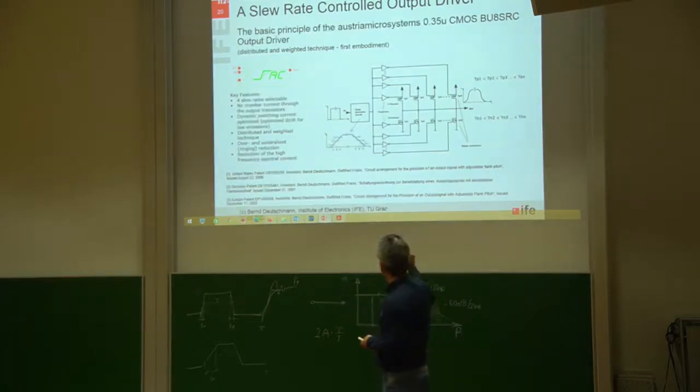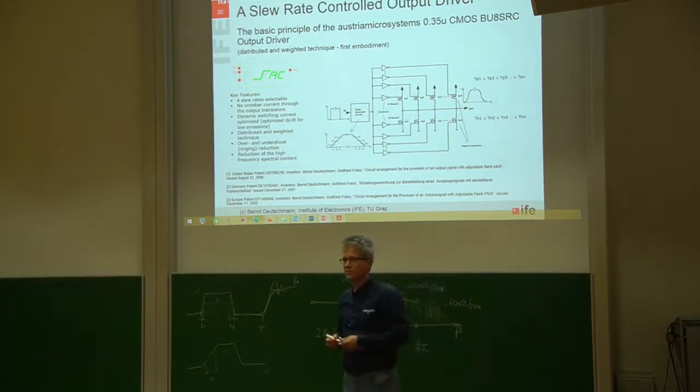Then a little bit later, in parallel, I'm turning on this next P-channel transistor, so the little bit bigger one. Then this P-channel transistor is turned on, and then in the final stage, the last P-channel transistor is turned on. And now here comes the resistance. So the on resistance of the first P-channel transistor, as it's the smallest, is the biggest.